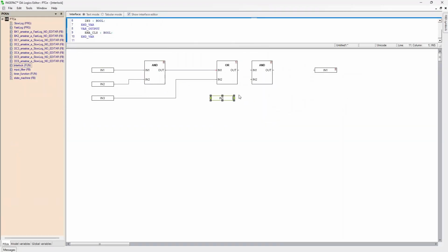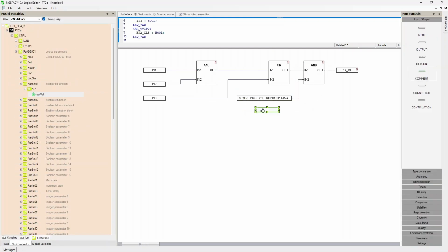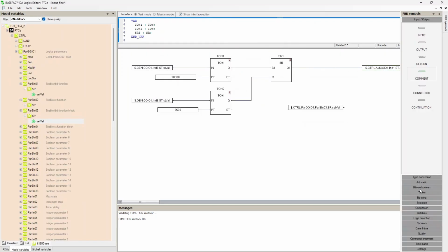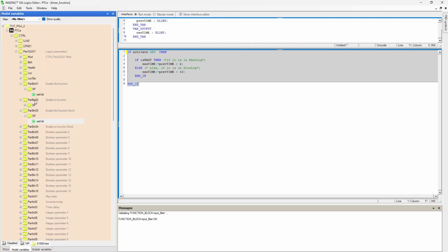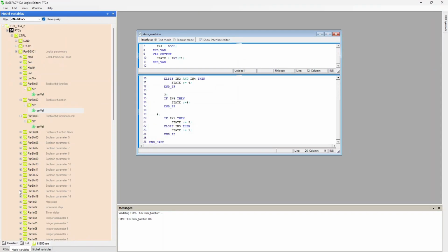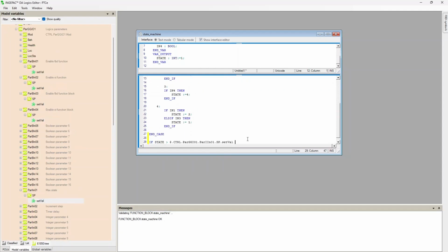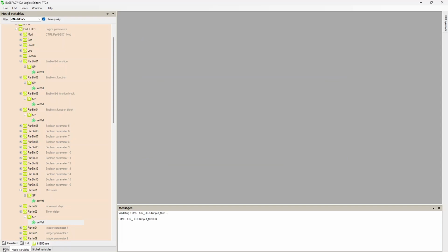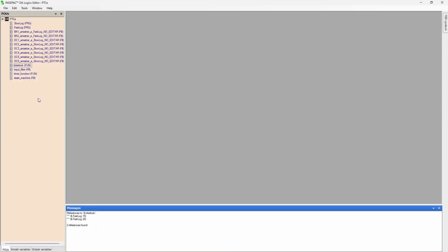For this example, the settings will be implemented in the following way. The first 4 Boolean parameters will be used to enable the 4 logical functions. 2 of the integer parameters will be used as a timer and threshold value. The floating value settings will not be implemented for this example. Once the settings have been implemented, the logics will be generated and sent to the IED.